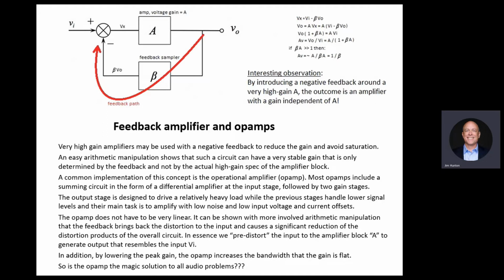Those create their own sound, their own distortions. And it's not negligible unless the original circuit, the main amplifier, is a very fast amplifier. Okay, now in phono stages, we want low pass and high pass to have the RIAA response. Well, guess what? Low pass and high pass involve capacitors. You delay the signal, whether you want it or not.